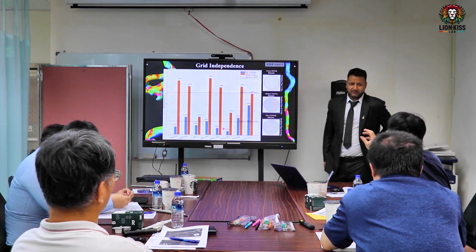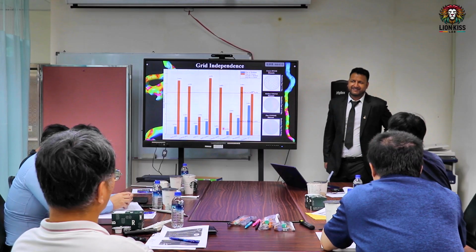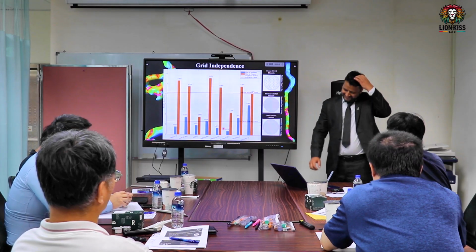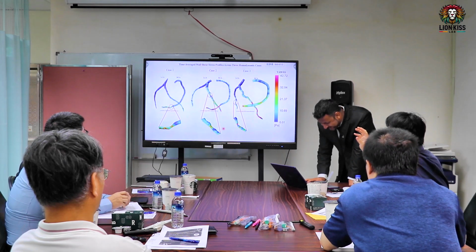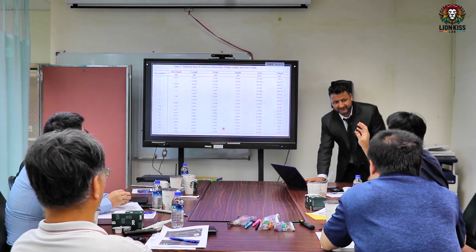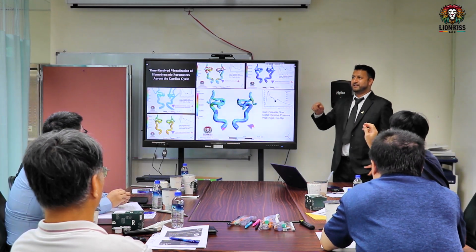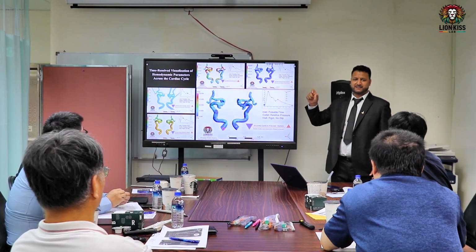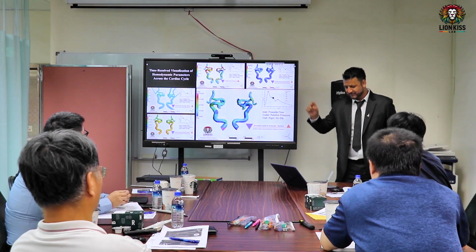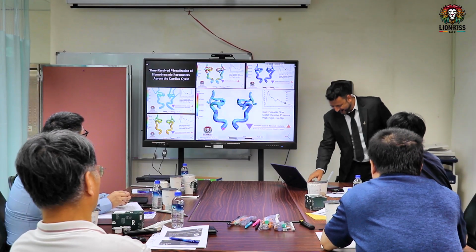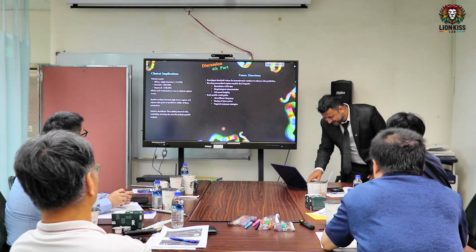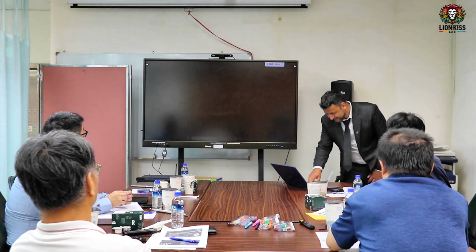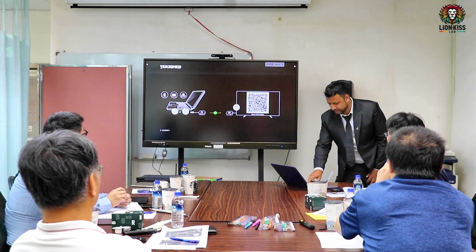Do you know the Courant number definition? Local velocity multiplied by the time interval, times steps, and this divided by the element size.